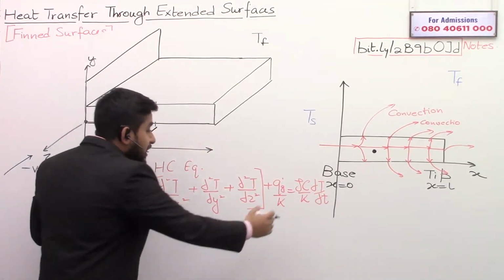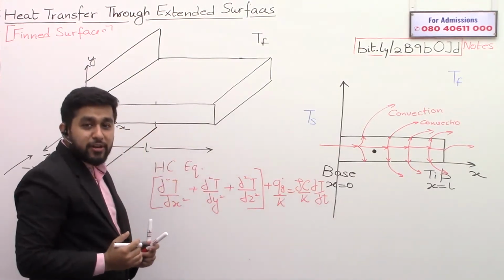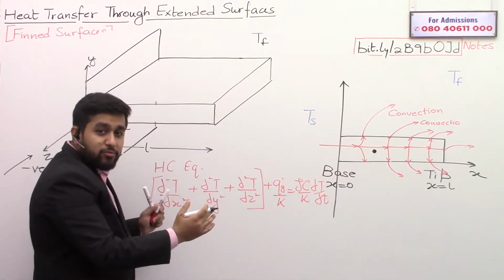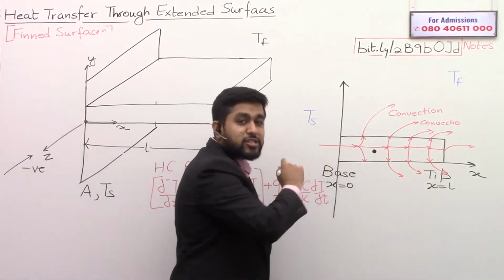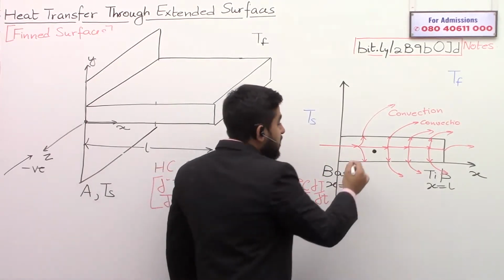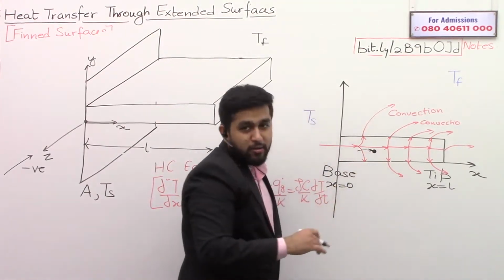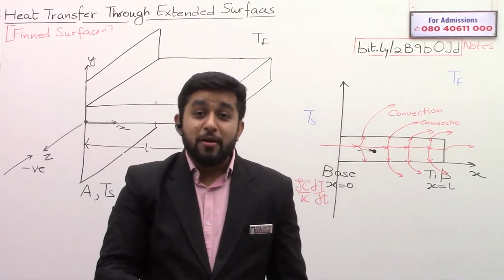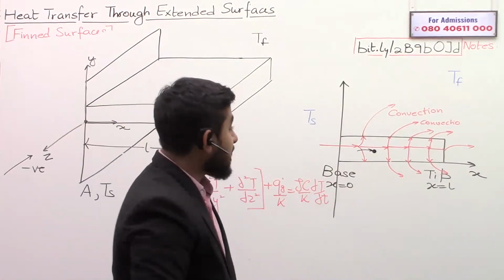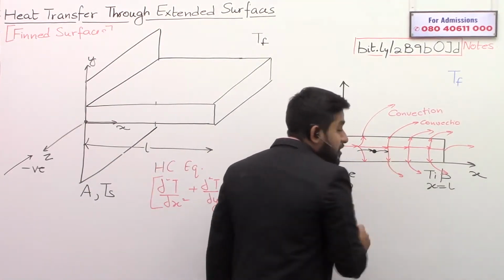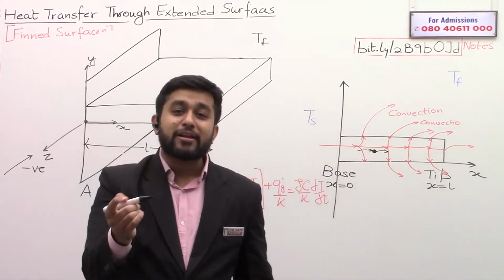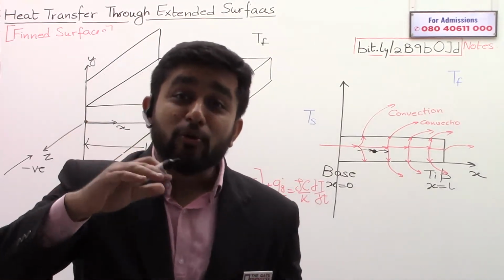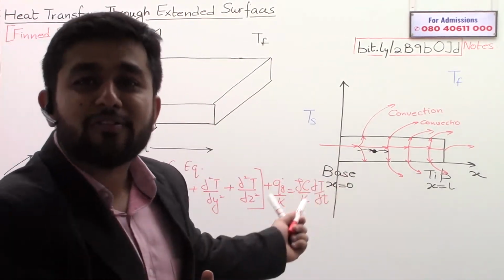So what this equation does is it relates these derivatives. And how do you write down this equation? Simply by energy conservation principle. So what you say, some heat will come inside the point by conduction, some heat will be generated inside the point by internal heat generation, and some heat will go outside. So you say energy coming inside minus energy going outside is equal to increase in energy. So this is how we write down this equation.